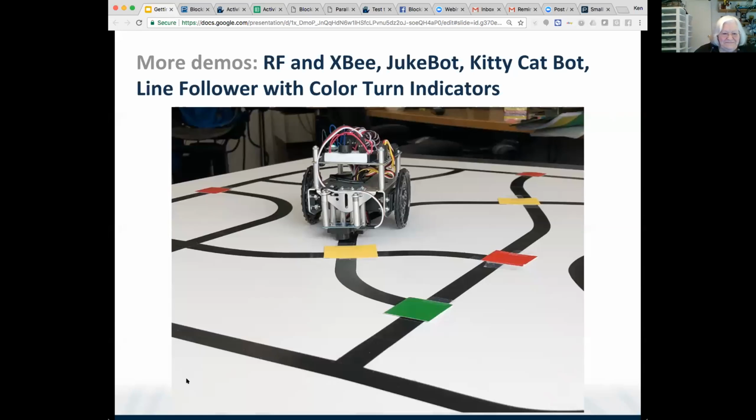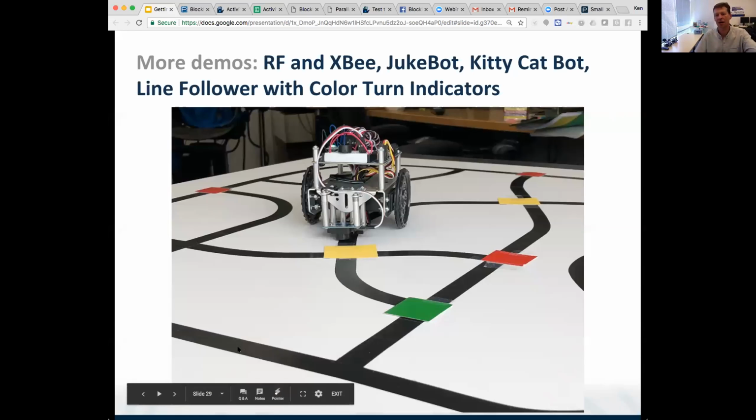Okay, so in this case, the program is actually quite simple, but basically you're reading the sensor and then you're sending out over RF three bytes probably, or I would say three variables. And the first one is an exclamation point, and then the second is the Y tilt, and then the X tilt. And then you turn those into drive commands on this robot. So some of these I think are published in C, maybe all of them are, and we're working towards getting them published in Blockly.